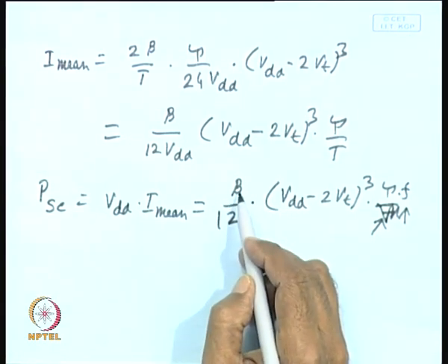You know, in beta we have the parameter that is mobility of electron, then we have the parameter width of the transistor, length of the transistors. So, the short circuit power dissipation is dependent on the physical dimension of the transistors, mobility of electrons and holes, the transition time, rise and fall time of the input, and the frequency of operation, and of course, last but not the least component is the supply voltage, because there is a factor of VDD minus 2 VT cube.